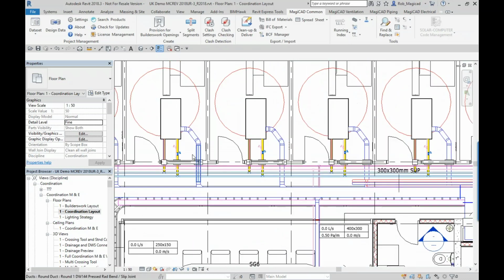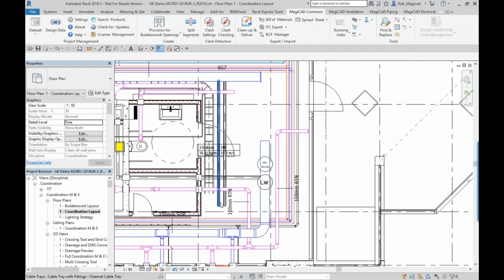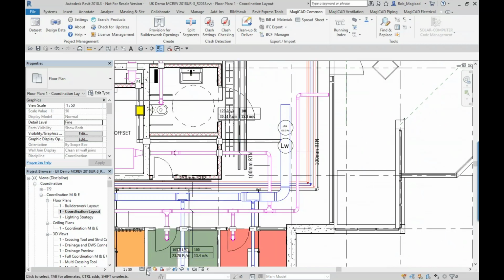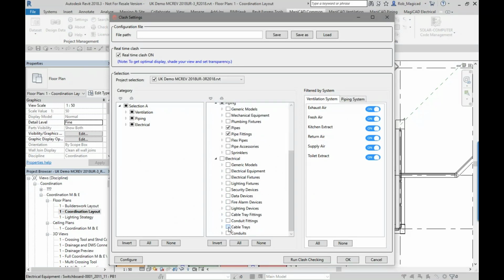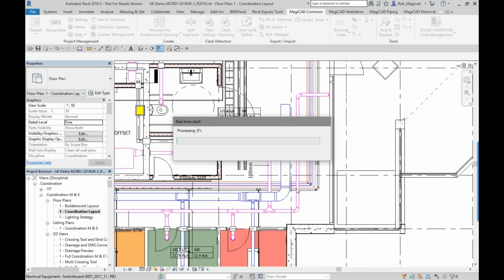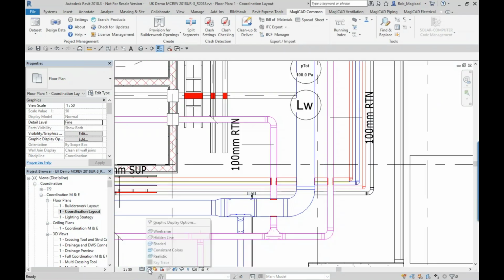So you can visually very easily see where you've got issues that are being created by clashes, whether with the architecture or with each other. And obviously that's the architecture side, I can then go and clash the MEP with each other as well, which I want to add in there now, and you can then update as I'm doing now. Anytime you want, you can just update the selections and then press OK. Now you'll see some more clashes, because obviously I'll have some MEP clashes going. You can see there I've got MEP clashes in there.